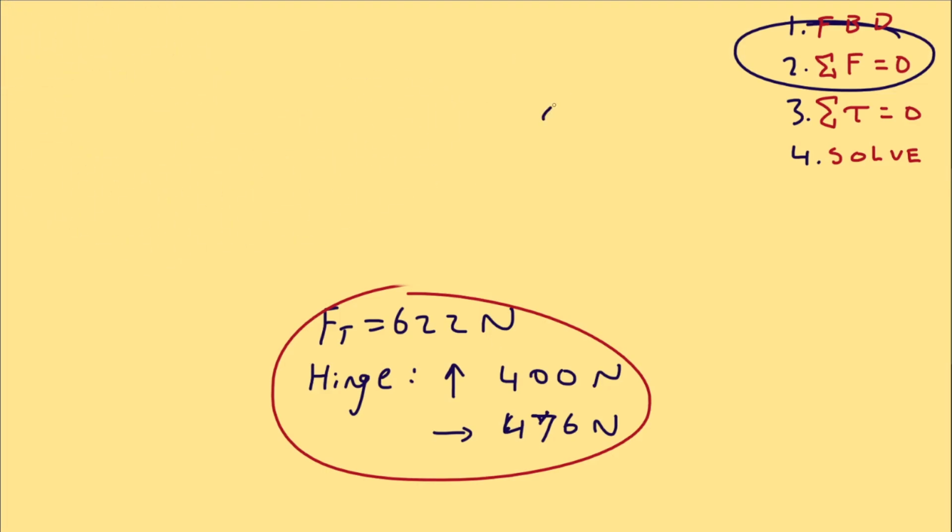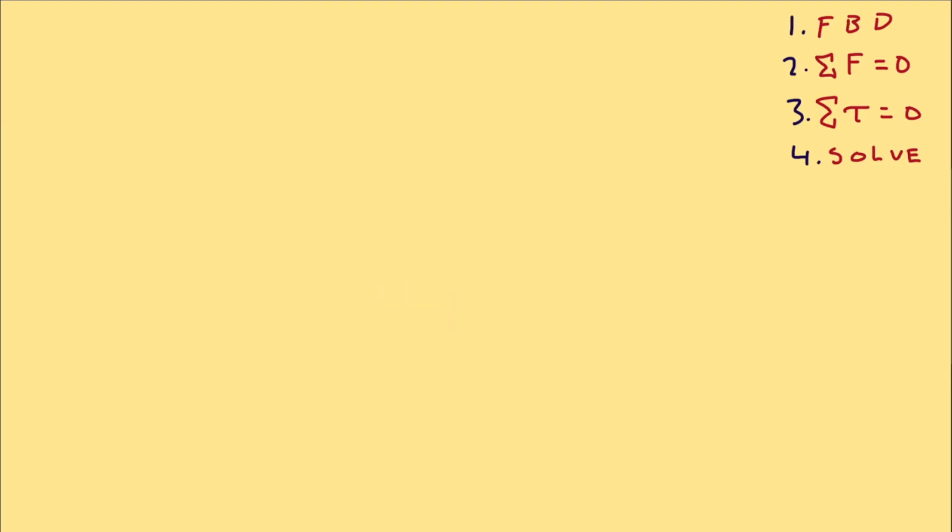To summarize, taking the torque around the hinge removed 2 unknowns instantly, and the hinge has to fight gravity and the sideways tension of the cable. The hinge is fighting that and counteracting it to keep our metal arm in place. Here's the final example we're going to go through.